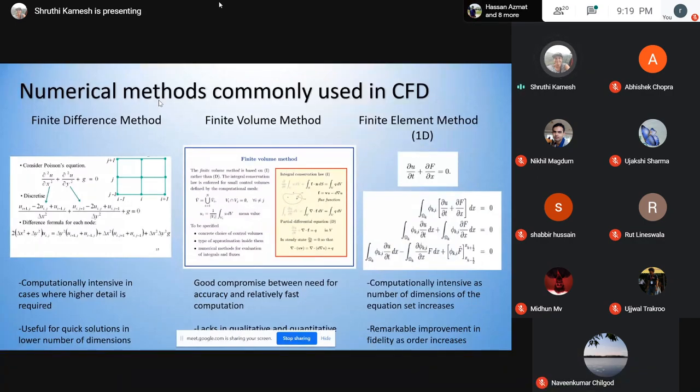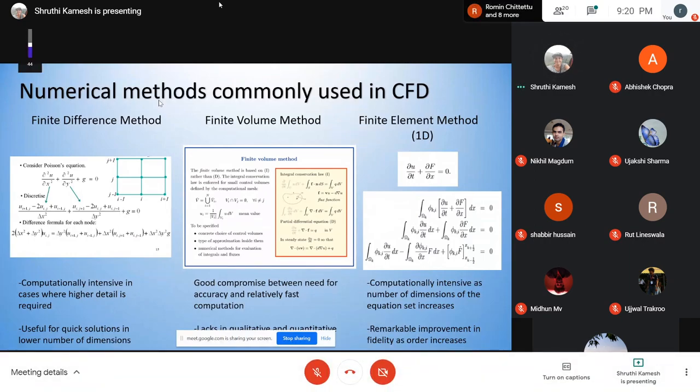And you cannot do that for all the points in a given surface, because it would be an infinite number of points. So you discretize it, which means you split it up into several parts, and you solve for those properties at each of those points. That kind of splitting is called a mesh.